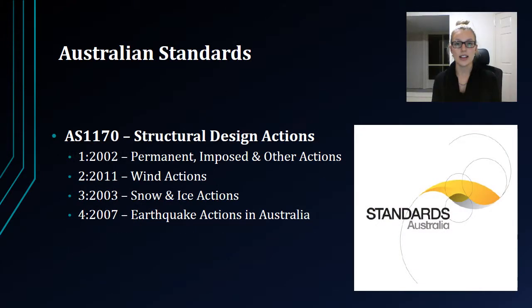The Australian standard that is used to calculate structural loads is AS 1170, Structural Design Actions, and is broken up into the following substandards. 1. Permanent, imposed and other actions. 2. Wind actions. 3. Snow and ice actions. And 4. Earthquake actions in Australia.